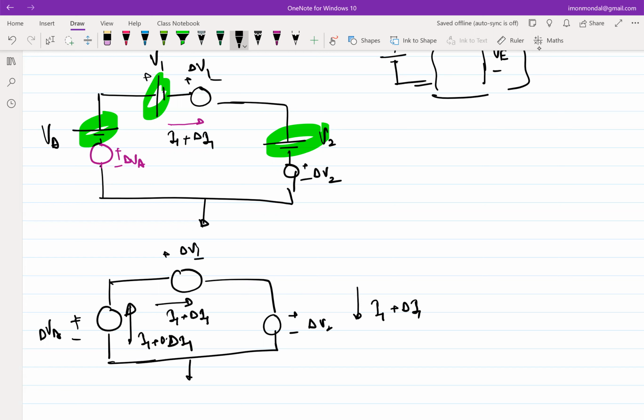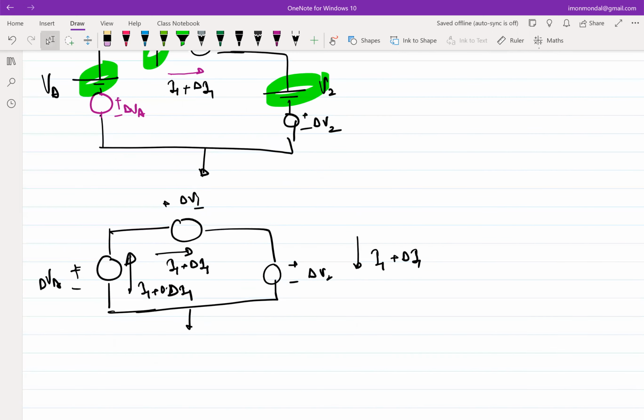Okay. So now I have to get rid of the current I1 in order to establish a relationship. So how do I get rid of current I1? If I add zero current to a node, in principle I'm not doing anything, I'm not perturbing the circuit. Now, there are different ways of adding zero current. One might ask, what do you mean by different ways of zero current? I can push some current in and pull that equal current out. That is one way of adding a zero current.